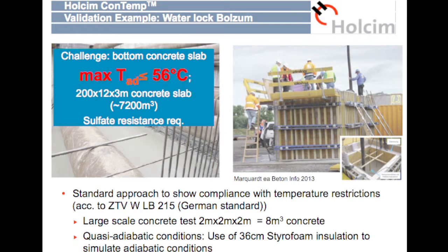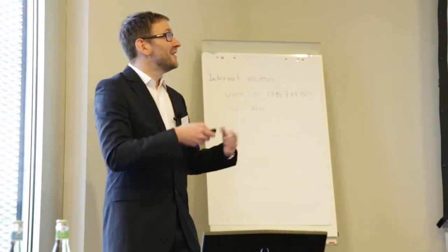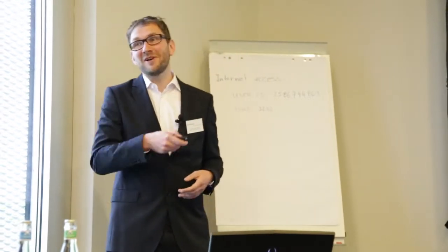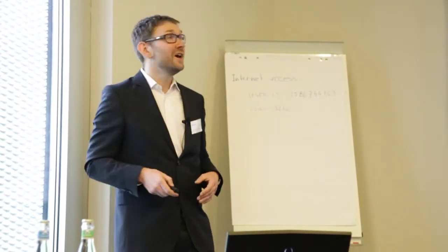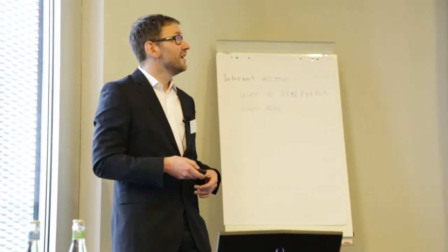To show that your cement or concrete mix design works, you need to do a huge-scale trial. In this standard, you have to do a 2 by 2 by 2 meter concrete cube. This is a bit bigger than the size we know from the concrete labs, and also a bit more heavy. Obviously, you have to move about 20 tons, and you do not want to do this experiment too often because, first of all, you don't know what to do with 20 tons of concrete all the time. It's tough to move, and it's also a bit expensive. So with that tool, you could minimize these big-scale trials to a small extent, and on top of that, it helps you to really optimize your mixing.